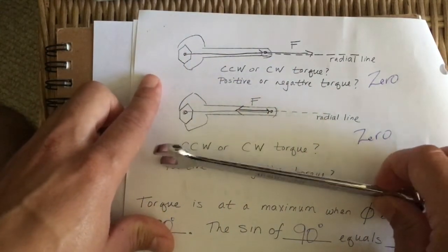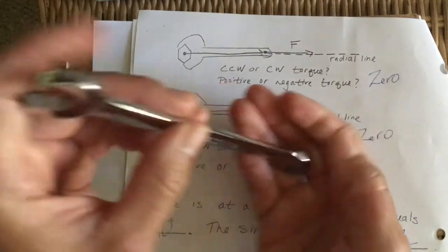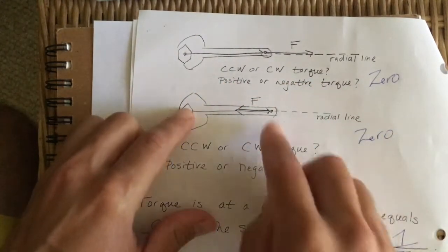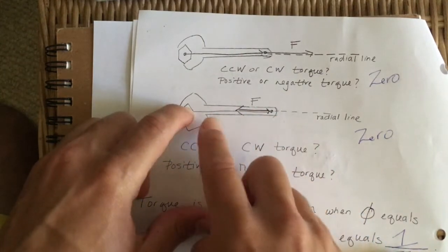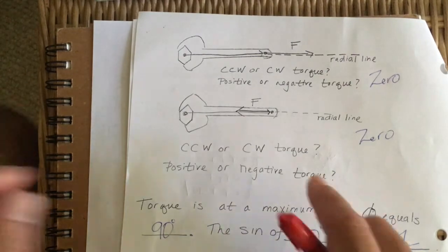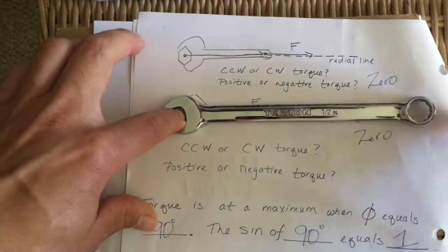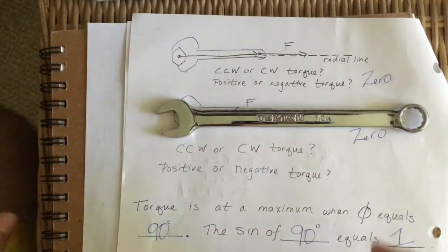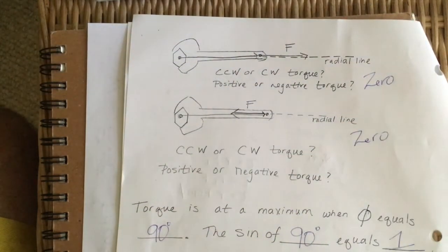And that's going to come up in the next part of the lecture as well, that when you have a force directed through the hinge or the pivot or the axis of rotation, you're not going to produce any turning force, which makes sense, right? If you came up to this wrench and started pushing this way against the nut here, it wouldn't turn it. And so you wouldn't bring it out of the board or into the board if it was say a screw or whatever you're trying to turn there.